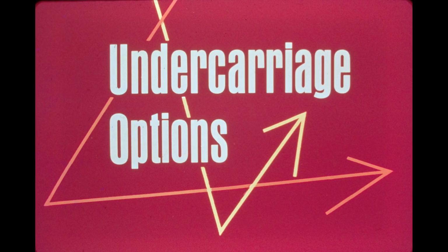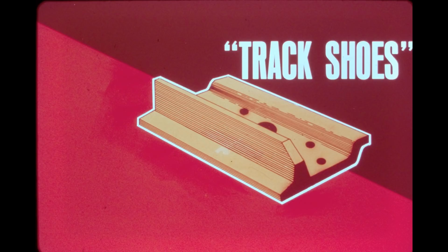After discussing standard undercarriage components and mounting, it would be beneficial at this point to look briefly at optional undercarriage components that allow a tractor to be suitably equipped for specific applications. For instance, there is a variety of track shoes for tailoring crawlers to work in certain soils and terrain. Track shoe design and selection is vitally important because the shoes provide the footing to support and distribute the weight of the tractor. They must do so regardless of soil density and composition or terrain.